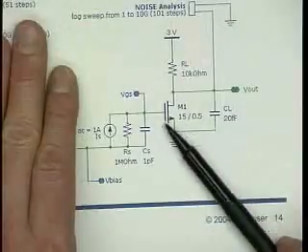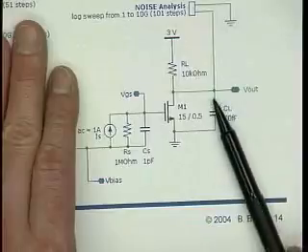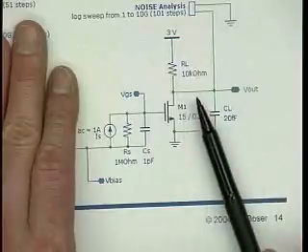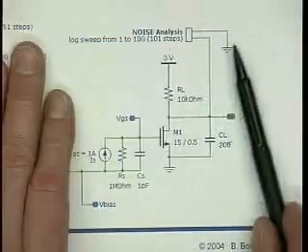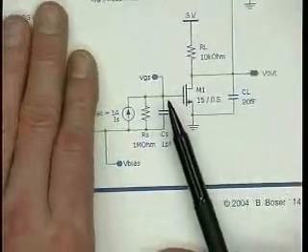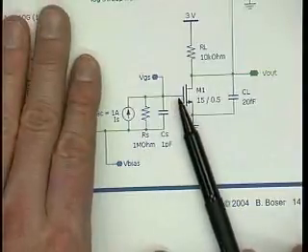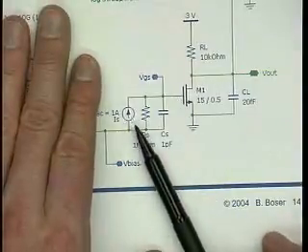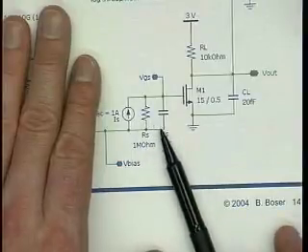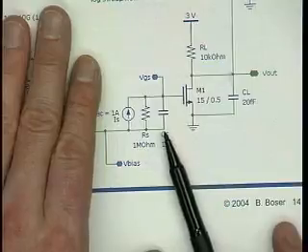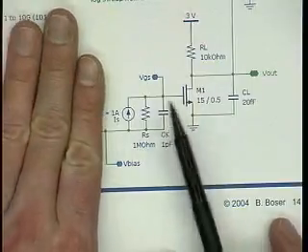It's a common source stage, resistively loaded, with a small load capacitor. I want to know the noise at the output here, so I use a .noise statement. This is driven not just by a voltage source hooked up to the gate, but instead by a current source in parallel with a finite output impedance, and also the parasitic capacitance of this current source.